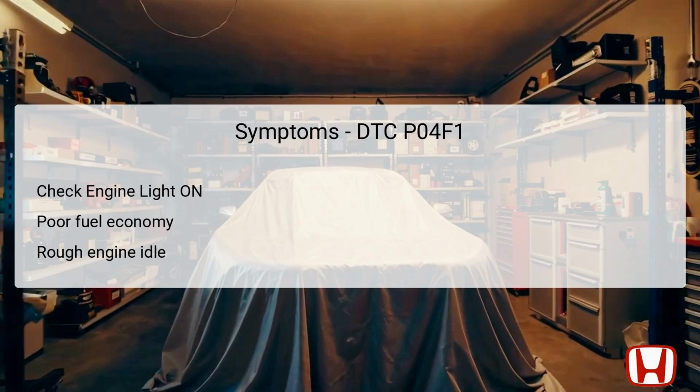The symptoms associated with DTC P04F1 can manifest in several ways, offering key insights into the functioning of the vehicle. Primarily, the check engine light (CEL) will illuminate on the dashboard, alerting the driver to a fault within the system. Additionally, drivers may notice a drop in fuel economy as the engine struggles to compensate for low vapor flow, leading to inefficient fuel usage.